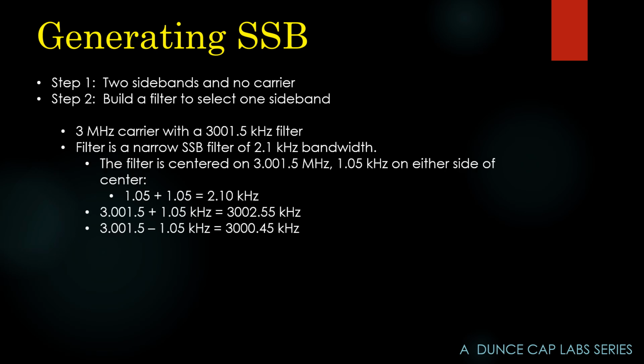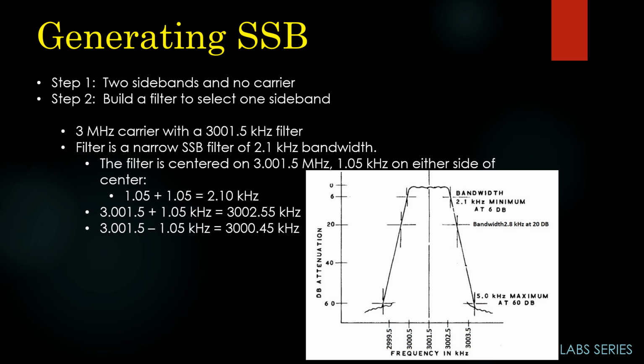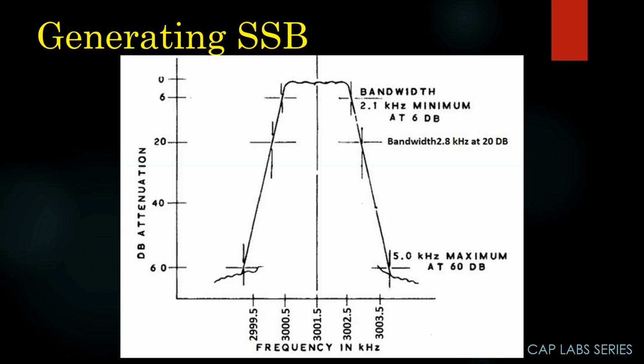That is 1.05 kilohertz either side of center. And there you have it. There's your filter. And yes, crystal filters can be that tight. This is a better look at the crystal filter's response.